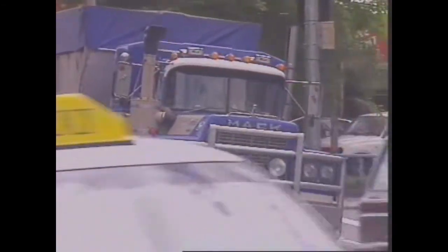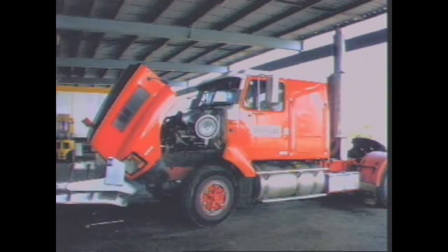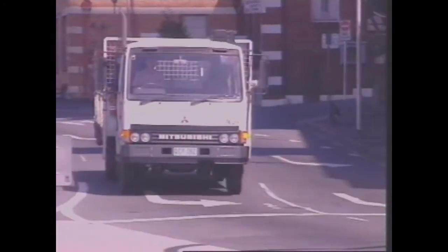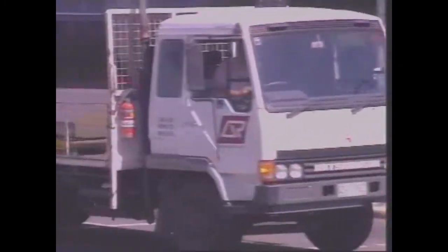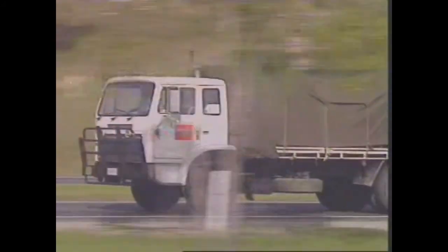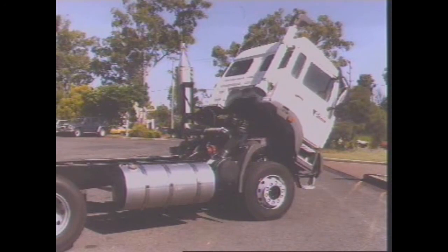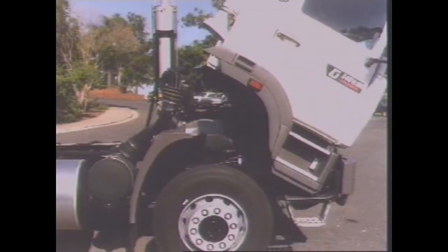Heavy goods vehicles can have normal control with the operator seated behind the engine. A lightweight bonnet that can be tilted or raised allows easy access to the engine for servicing. In forward control, the operator cabin is mounted over the engine. This design gives greater load length to the vehicle. The cabin can be tilted for easy access to the engine. Some designs only have a hinged flap over the engine bay.